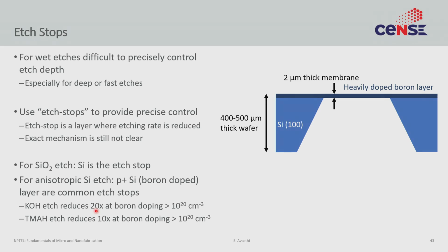There are several etch stops. This is not the only one. And often if you are trying to do very fine etching, where you need to end with very thin membranes, it's often recommended that you use etch stops instead of just using a stopwatch and trying to time the etch.